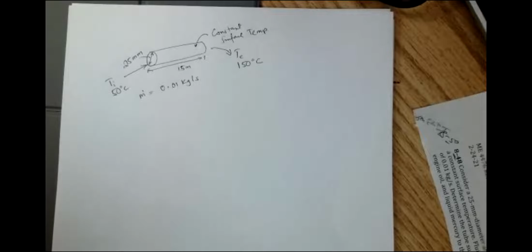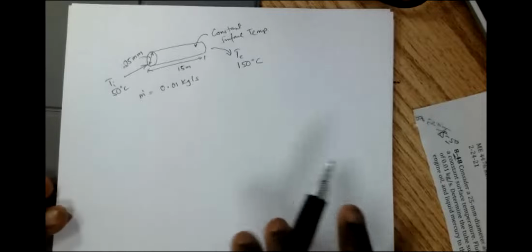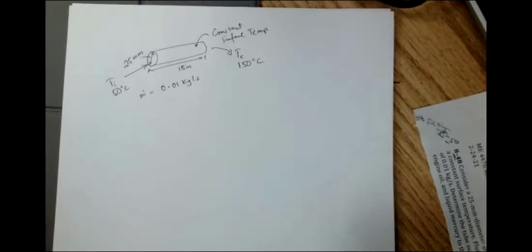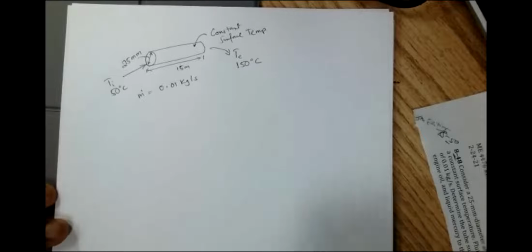So when the fluid enters the tube, the 15-meter long tube, just like we had in the hydrodynamic boundary layer, we have a hypothetical boundary surface which divides the flow in the pipe into two regions. Okay, we have the boundary region which we are going to consider, and then we have the irrotational flow region. This is where friction is negligible and where velocity is essentially constant, especially in the radial direction. And the thickness of the boundary layer increases as the flow moves on in the pipe.